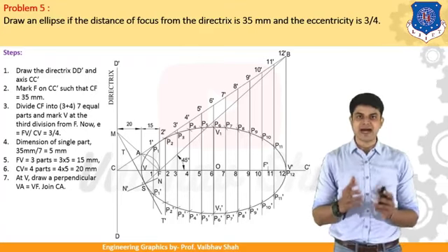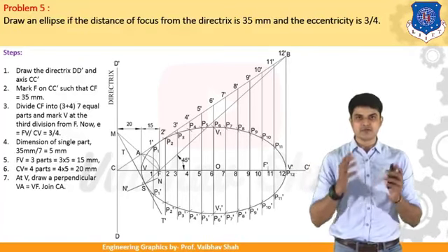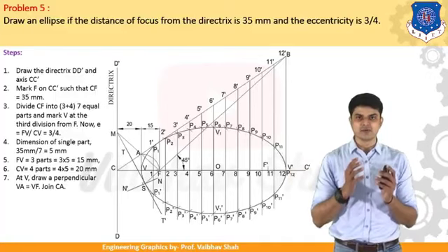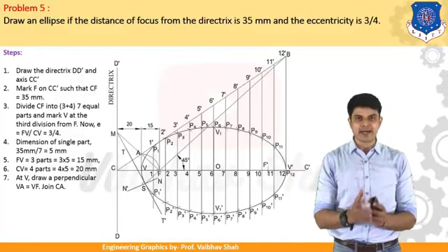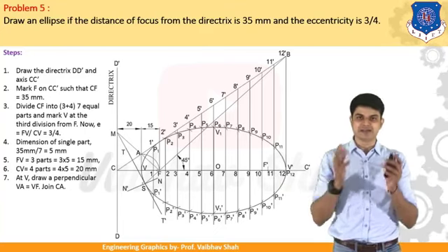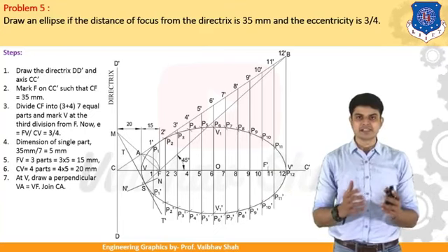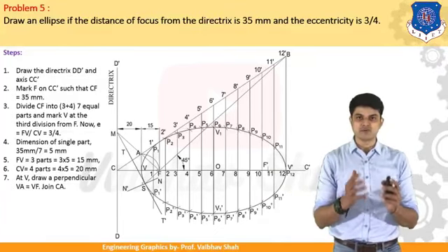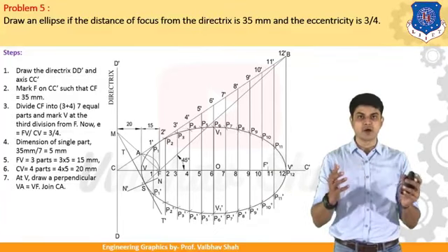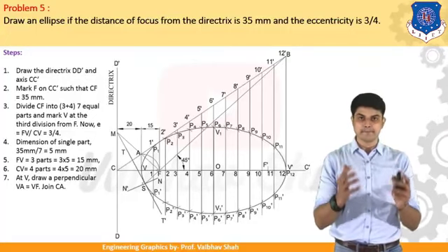Similarly, try to find out the arcs for each of the points until you reach your final vertex point. So you will be having a number of points generated until you get the P12 point. And after getting your P12 point, you should simply connect these points by a dark smooth line, either by the help of a French curve or you can join it by a smooth line. So you will be having one curve generated, which is nothing but what? It is your ellipse generated by the Directrix focus method.